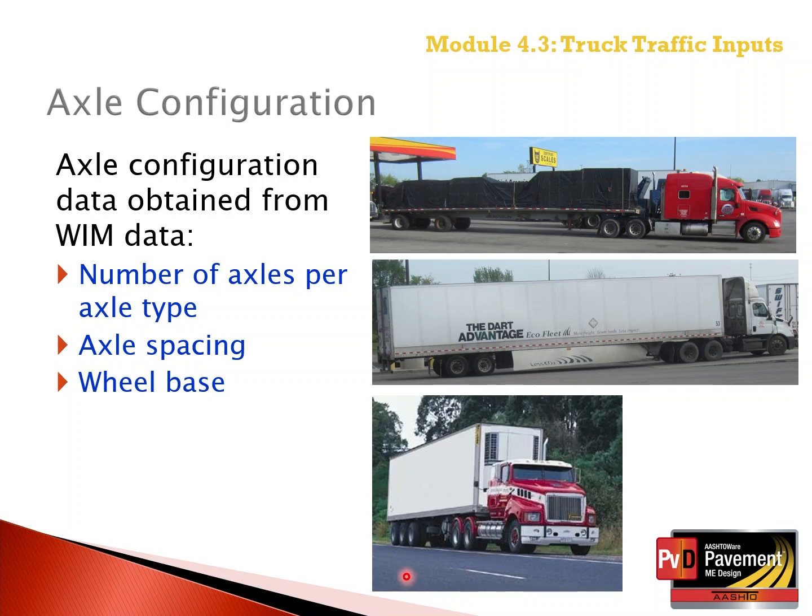The defaults for the wheelbase inputs, length and the percentage of trucks within each wheelbase, are given in the manual of practice, but they're 12 feet for short wheelbases, and 17% of the trucks are assumed to have a short wheelbase, 15 feet for medium wheelbases, and 22% of trucks are assumed to have a medium wheelbase, and 18 feet for long wheelbases, and it is assumed that 61% of trucks have a long wheelbase. So those are the default values.